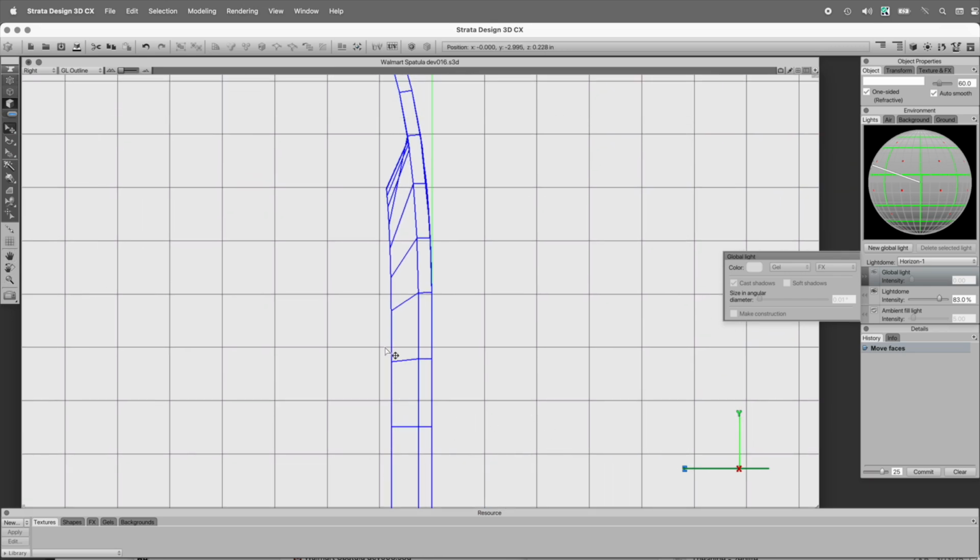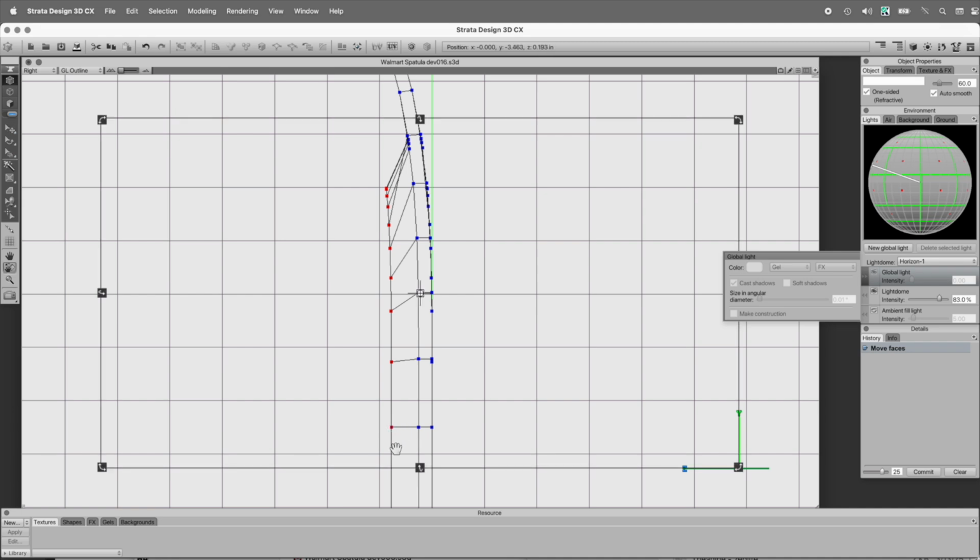But one thing I'd like to do that I see on the original physical object is there's more of a curve here. So on the spatula itself, it's like there's more of a curve here to sort of prevent food from coming up. So let's go ahead and do that. So let's take just these polygons here. And I think I don't want anything to be affected beyond there.